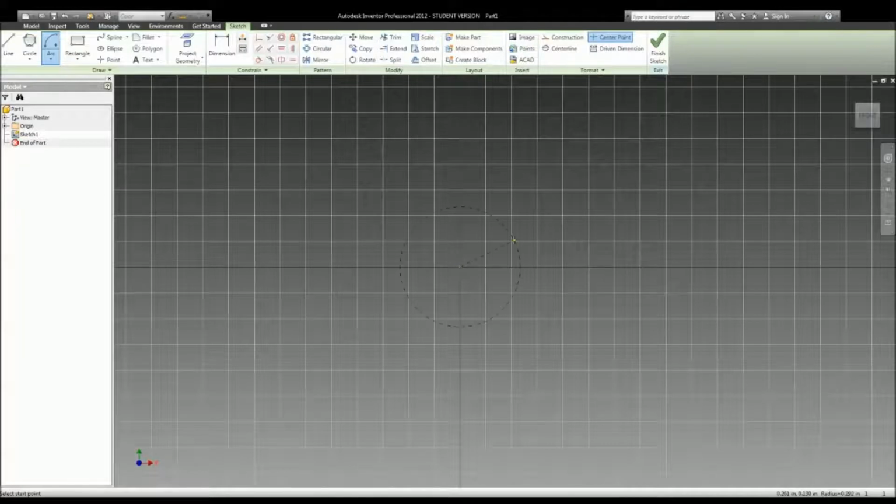So you have a center point, draw out the radius of the circle that you want, and then it tells you the angle that your arc will be at. So right now my radius is 0.5, and the degree that my arc will be is 137. And if you click, it starts you right there, 137 degrees from 0 at the specified length that you wanted.